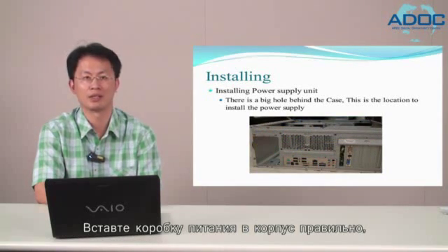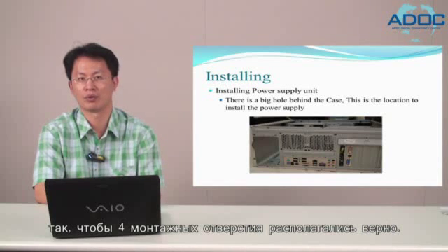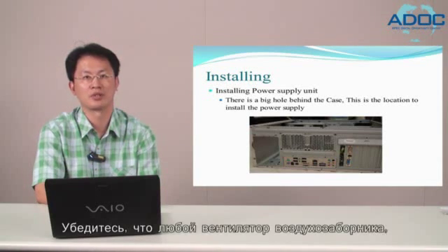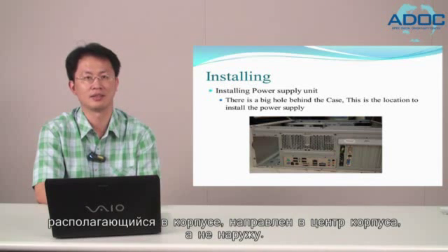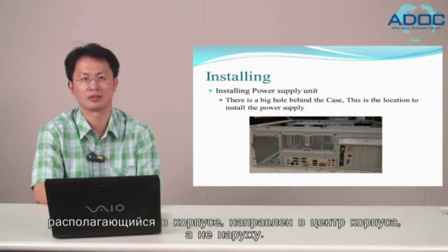Align the power supply into place in the case so that the 4 mounting holes align properly. Make sure that any air intake fans on the power supply that resides in the case is facing toward the center of the case and not towards the case cover.